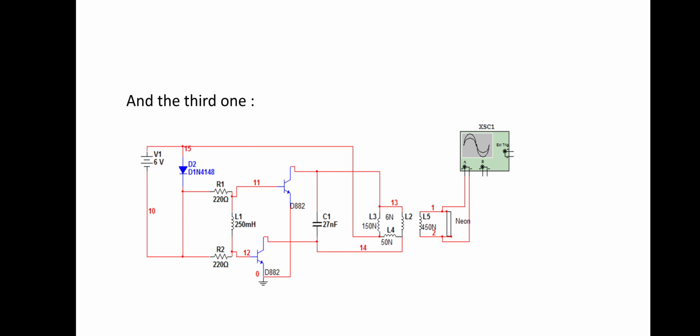If terminal 1 is at positive potential with respect to terminal 3 at any instant, terminal 2 will be at negative potential with respect to 3 at that instant, because terminal 3 is grounded. Therefore, points 1 and 2 are out of phase by 180 degrees.